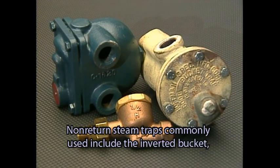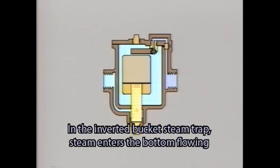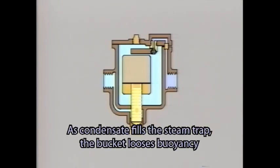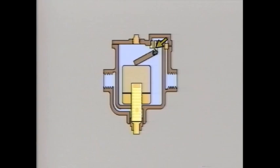Non-return steam traps commonly used include the inverted bucket, the thermostatic, and the float thermostatic. In the inverted bucket steam trap, steam enters the bottom flowing into the inverted bucket. The steam holds the bucket up. As condensate fills the steam trap, the bucket loses buoyancy and sinks to open the discharge valve.